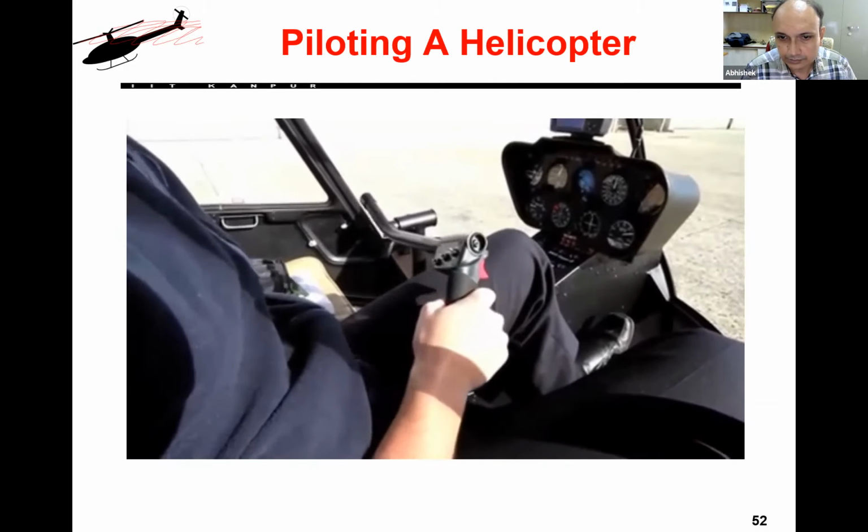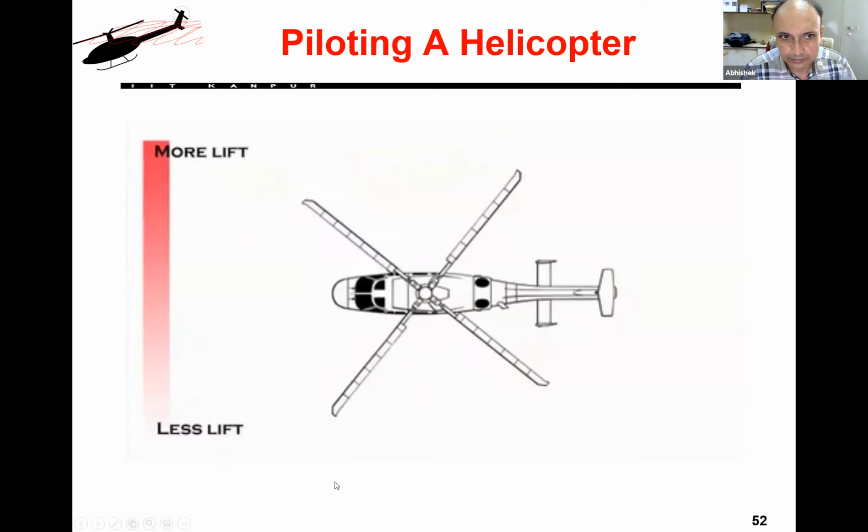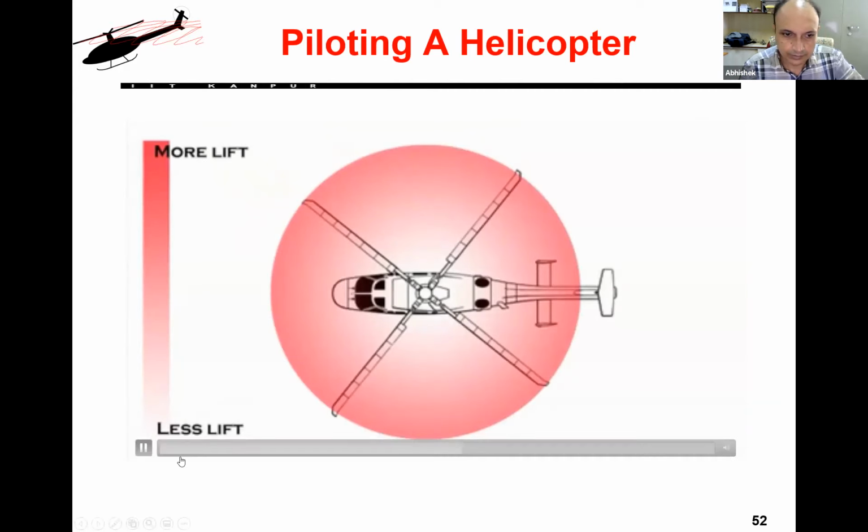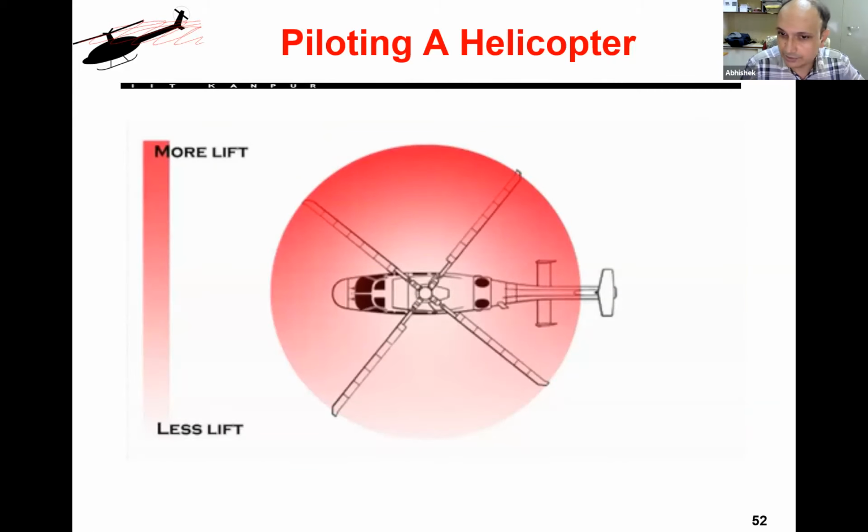Here's how it works. Here's a top-down view of a helicopter in flight. In a stable hover, you can look at the main rotor as a fairly evenly balanced disc of lift. When you want to move off in a particular direction, you do it by creating extra lift at one particular point in this disc. And here's where we come back to that incredibly clever swash plate, which was invented by Juan de la Cierva for his autogyros.